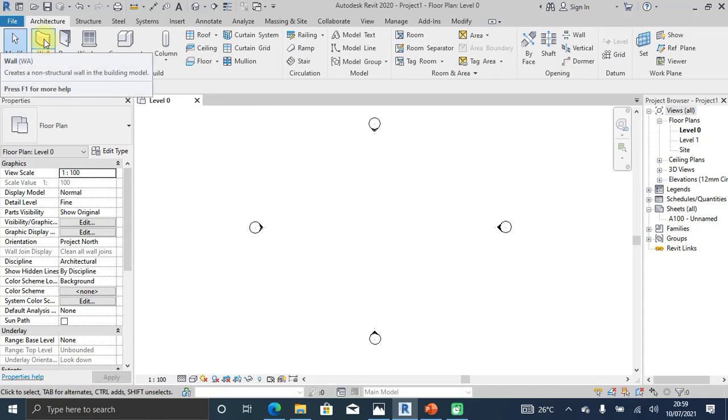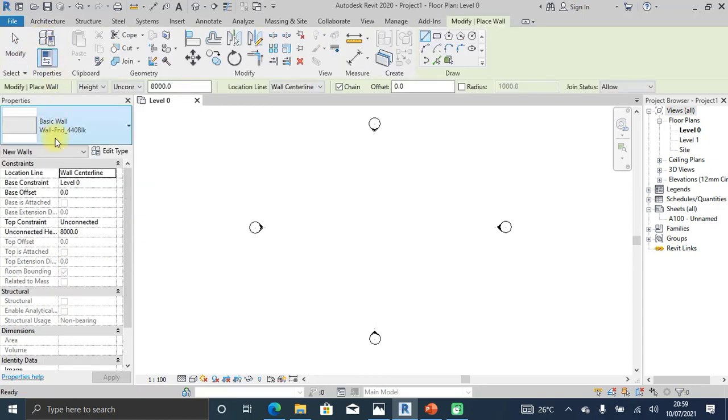But now clicking on the command itself gives you this property tool palette with all the type specifications. And then you see that the conceptual tab also opens, where you can access tools you would use to apply the selected wall appropriately. And then you also have these quick access parameters about the wall right on top of this window that you can access. So we are starting off with selecting the wall type.